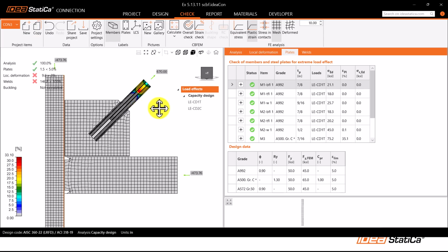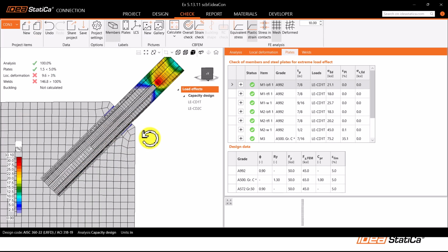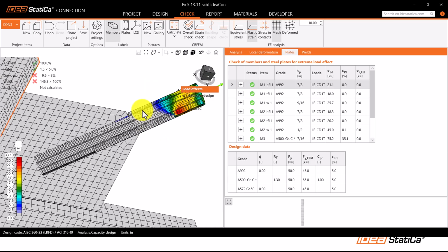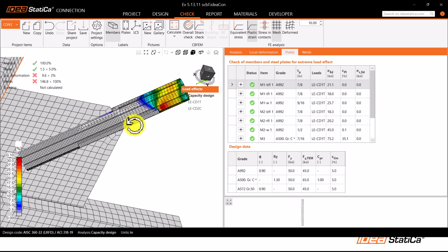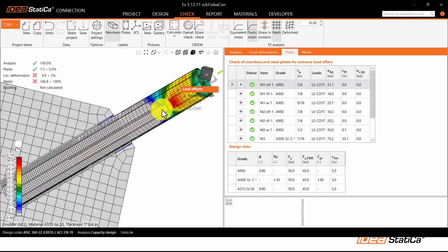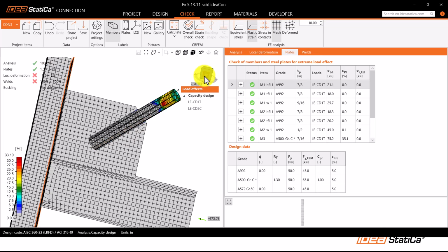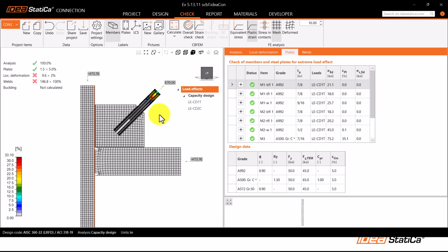You can see that basically we push out the plastic hinge happening in this area. So it's just at the end of the reinforcement plate. So we can say that we are confirming the plastic hinge happening here. That means the yielding on the brace with the tension force is happening.